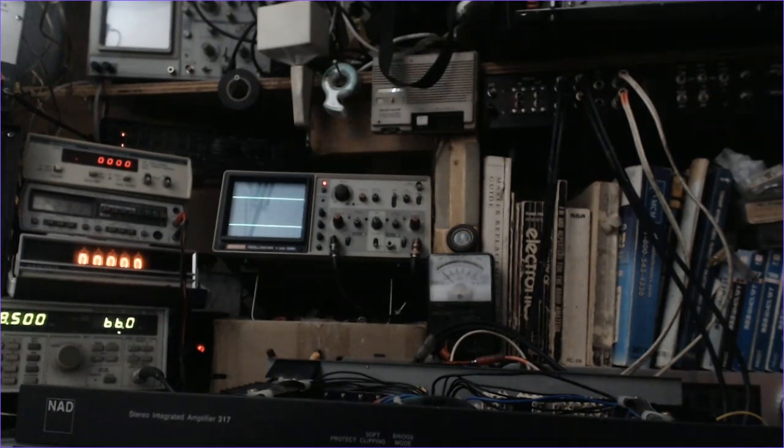They are the 0 points of a horizontal bar graph, which is going to represent the amplitude that is in parallel with the oscilloscope, and it's going to show us in decibels different changes. It's a lot easier than trying to interpret changes in the oscilloscope amplitudes. And it's also going to allow us to perform frequency response tests, and it's also a distortion analyzer.